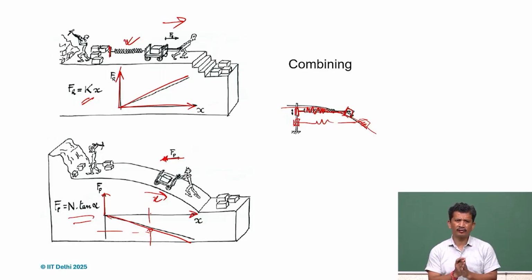Many times, suppose you are looking for zero stiffness so that it can stay anywhere, or for vibration isolation cases, or for some vibrational characteristic, we may want a very small k, and in those cases it's very difficult to directly design something with very low stiffness. But if we combine the two, we can get near zero stiffness and fine tune the vibrational behavior of the system.